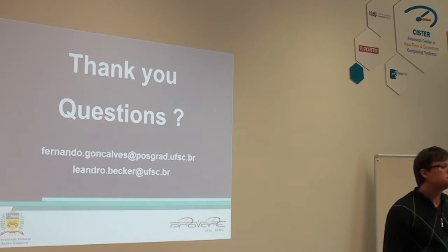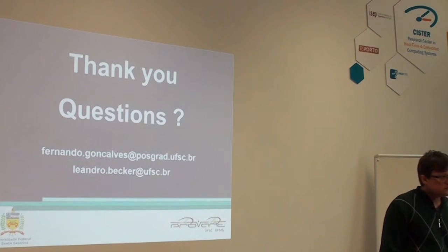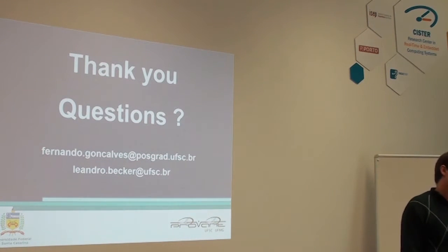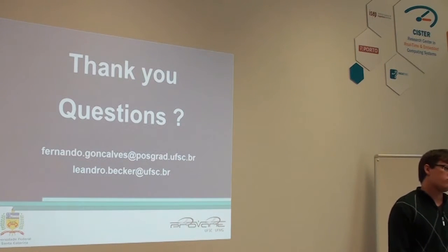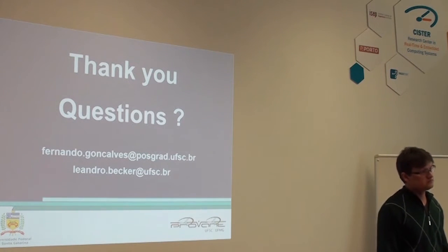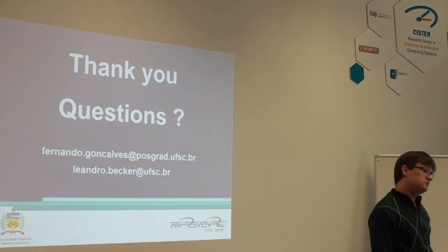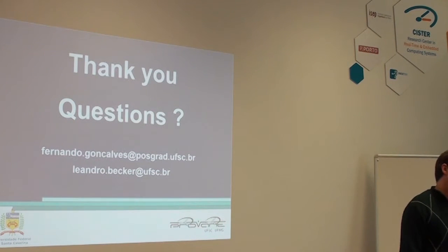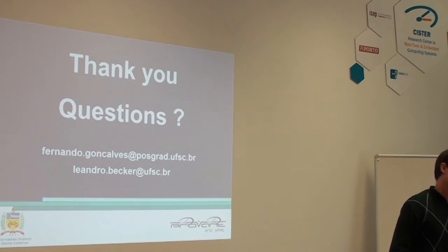Do you integrate any type of timing analysis in your framework? Because for this kind of application, which are basically controlled, the response time of your control loop is very important for the stability of your system. Currently, I've seen that in this framework, we're basing everything on the refreshment rate of the data coming from the inputs, and what is required by the output, but I suppose the end-to-end response time is also important.